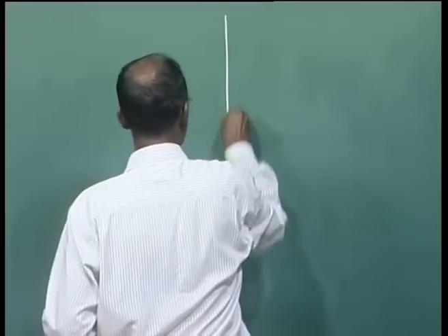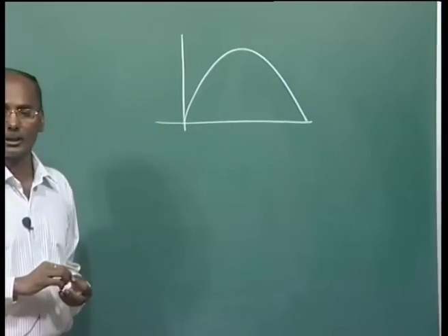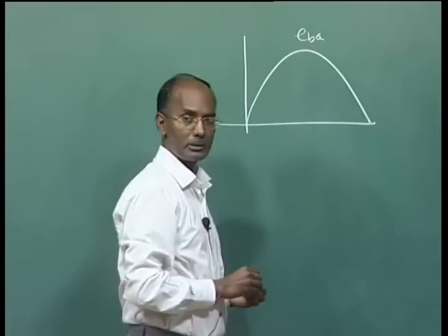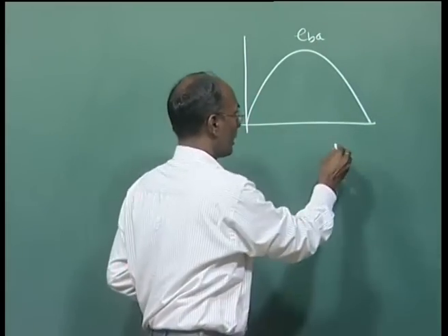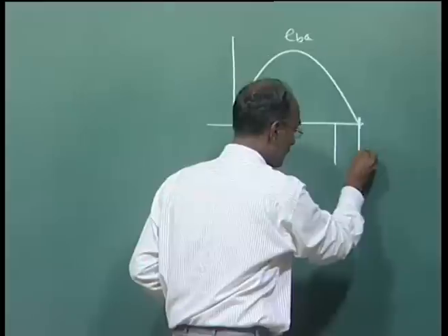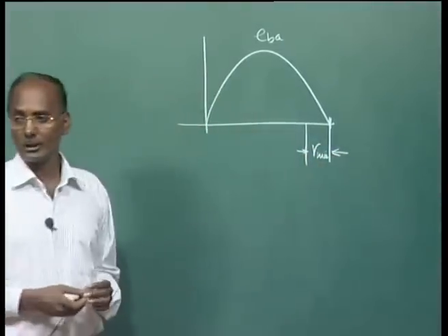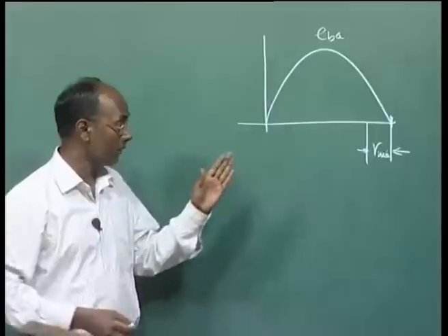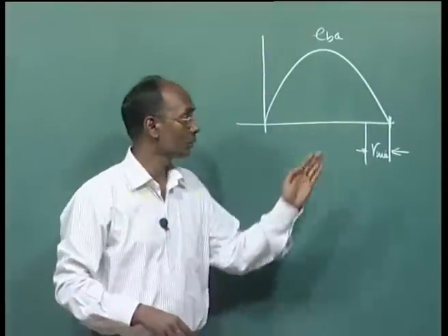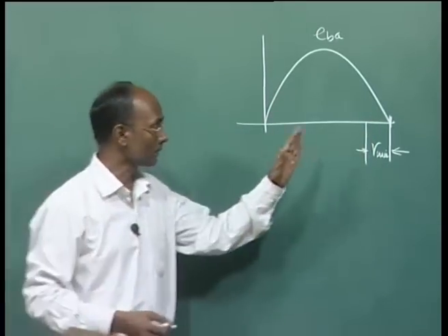So, in the CEA control, this is the commutation voltage of any valve, and if I am writing this for valve 3 it is EBA, and this is the zero crossing. Basically, we are maintaining this period, that is gamma minimum, so that the commutation can be successful even during the time after firing, if U is changing. So, we should land up here and the commutation should be successful.